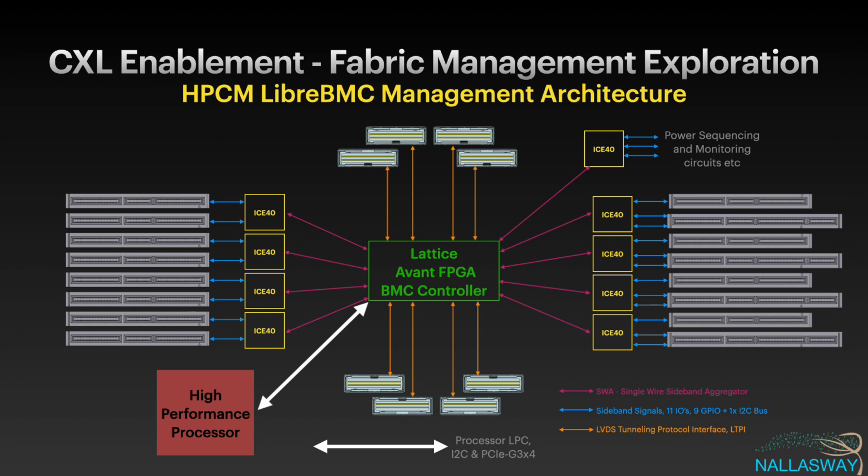And so this diagram is showing that we've chosen Lattice for this approach, and we're using their iCE40 devices to really compress all of these sideband signals, which there are quite a few of with all these interconnects, into this single wire aggregator.